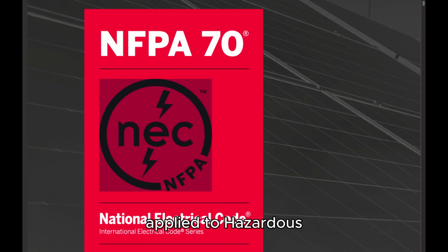CMP14 Process seal, as applied to hazardous classified locations. A seal between electrical systems and flammable or combustible process fluids where a failure could allow the migration of process fluids into the premises wiring system.